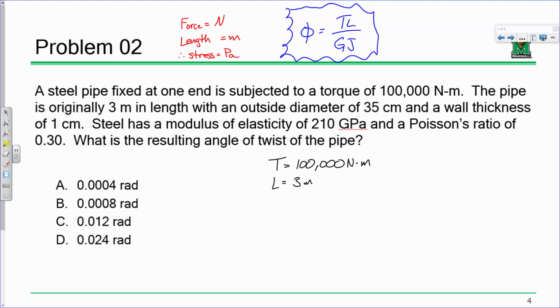It bulges out, right? So in reality, it does that. Imagine the other way around. Imagine you've got a piece of taffy in your hand. You take that taffy and you stretch it. It gets longer, but what else happens? It gets thinner. Poisson's ratio tells you the relationship between those two. If I take a piece of steel and I stretch it, it gets thinner and it gets longer, but the ratio between those two is about 0.3. In other words, its strain this way is about 30% of its strain that way. That's what Poisson's ratio is, and that's a material property.